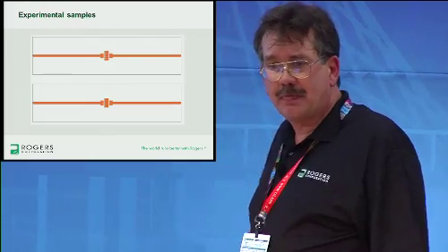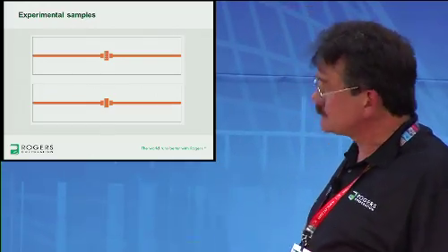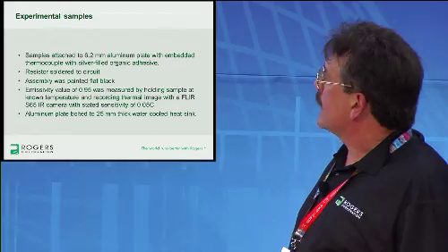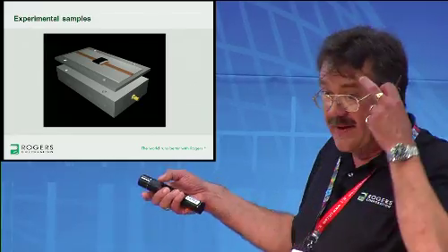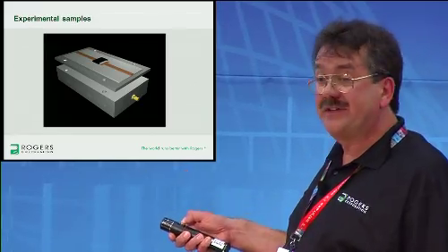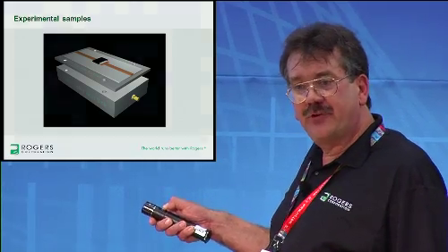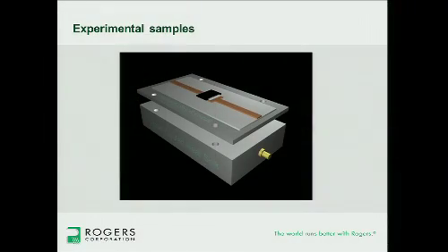These are 30 mil holes with a mil of copper plated, to the ground plane. We take those circuits with the chip resistor soldered on, glue them onto a 1/4 inch aluminum plate, which then gets bolted to a water-cooled heat sink.